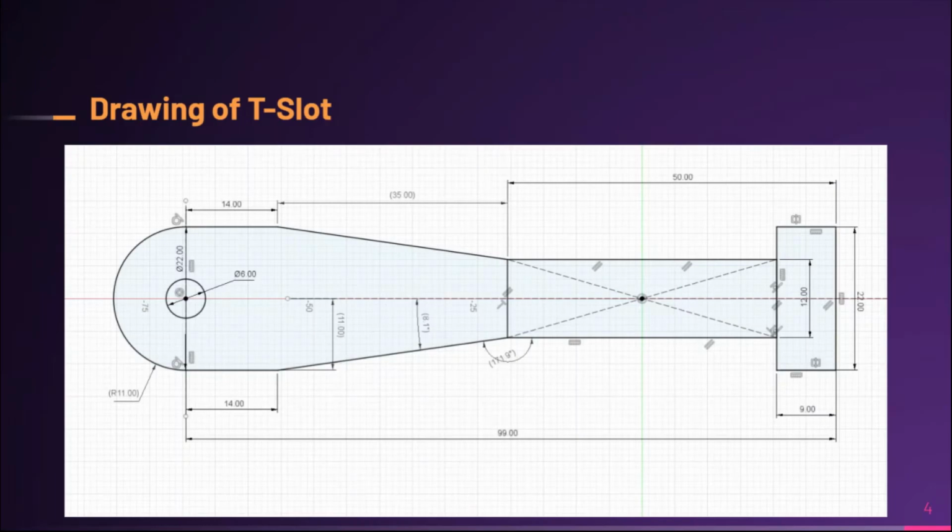As you can see here, I have created a sketch on Autodesk Fusion 360, which is a powerful, collaborative, cloud-based CAD software. You can see the dimensions for every line and arc listed as depicted in the orthographic drawing provided. Certain dimensions are driven dimensions, which means that they're not critical to determining the geometry and are only there for your understanding. These dimensions have been marked with brackets.